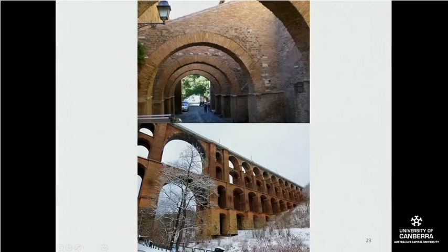So, what's bad about brick? Well, it's porous, so if you don't build a thick enough brick wall, then the water will be able to get through and spoil your wall finishes on the inside. It can also suck up water from the ground through capillary action. So you need damp-proof courses to stop the water from crawling up through the bricks.